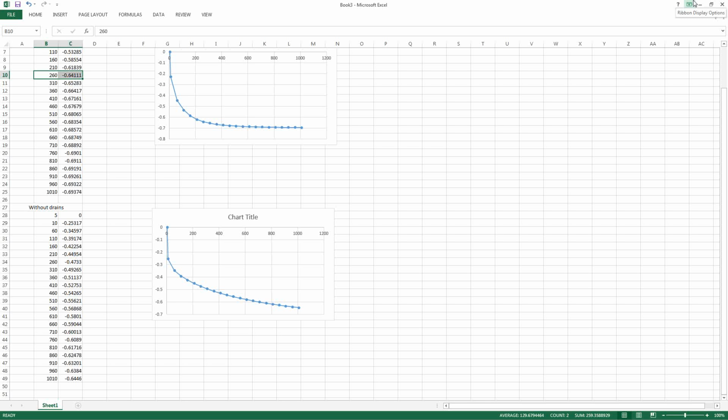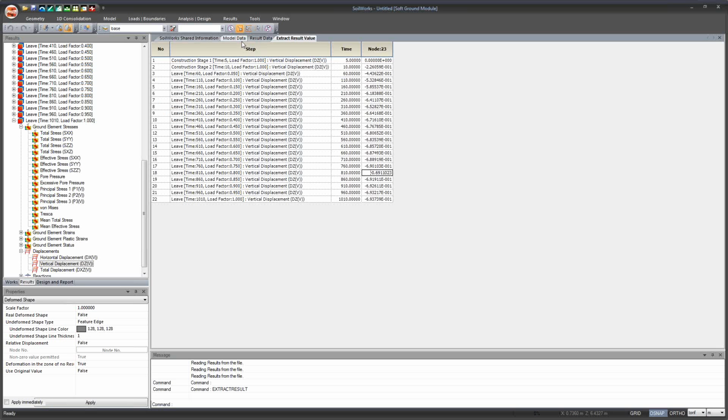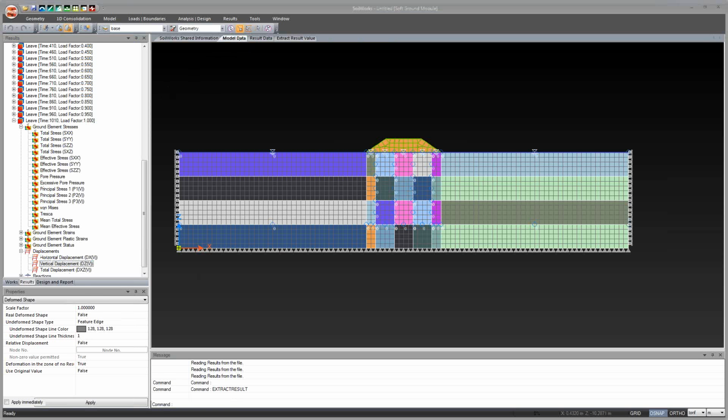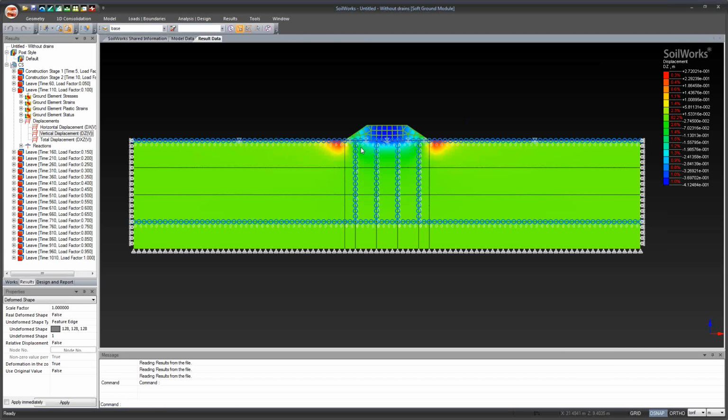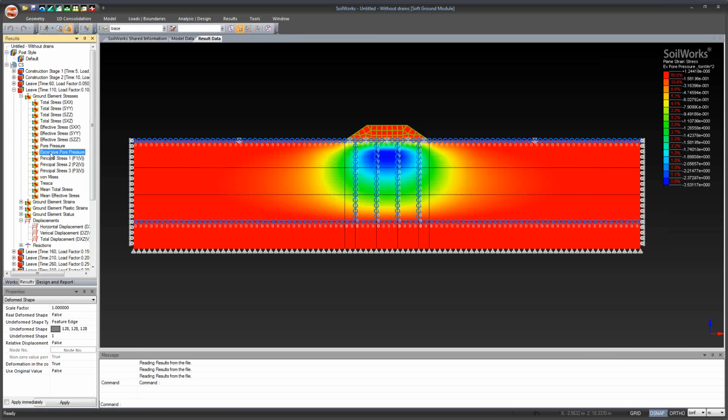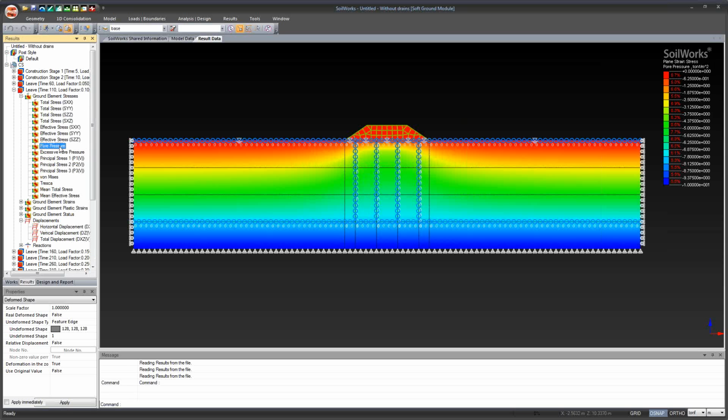Now the advantage of finite element analysis is that first of all, it's a 2D analysis, that is, even as the settlement is happening, you get the contour plot in both directions, as I will show you in the program. Also you get the pore water pressure variation, as I already told you in the program, so how the pore water pressure variation is taking place could be considered. Fine, so this can also be done.